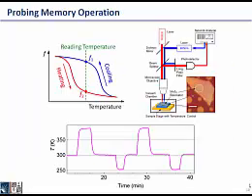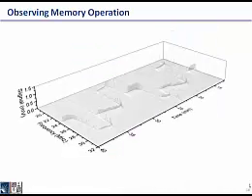We read out the device resonance using an optical driving and optical readout technique, basically using a two-laser system. The driving laser is controlled by the output of a network analyzer, and the readout signal is fed to the input port of that, and we sweep the frequency and see where the frequency response is, where the resonance is. I'm going to show you, when I apply a series of heating and cooling pulses to the device, how this hysteresis loop gives me memory-like behavior.